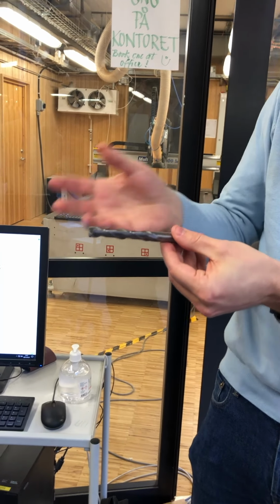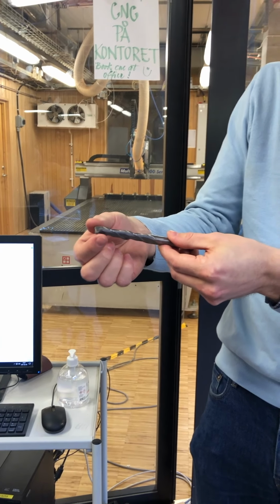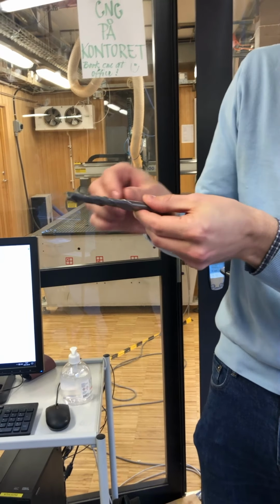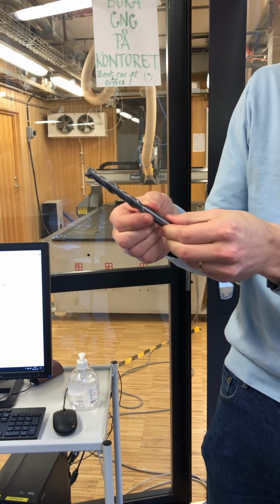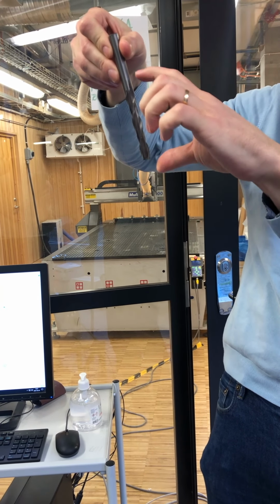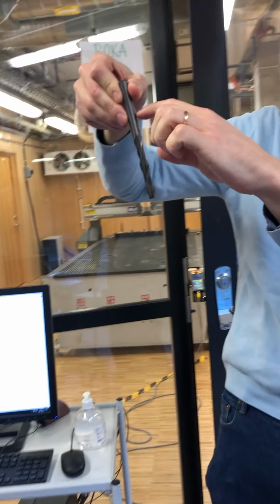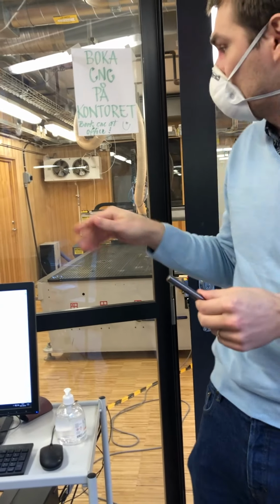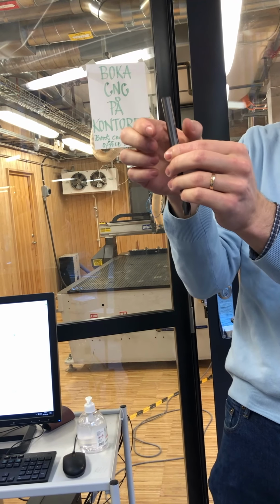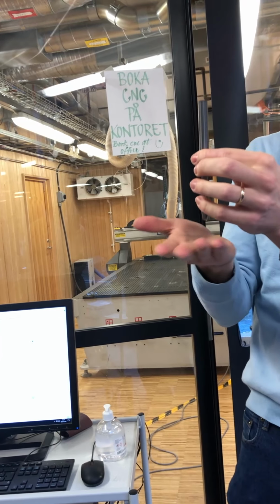If it's constructed in an adequate way, then the cutting diameter is within tolerance at least a little wider than the shank, so that if you cut deeper through the material than the cutting edge, then it won't lead to friction. But you will need to check this because some of the end mills have a wider shank than they have a cutting flute or cutting diameter.